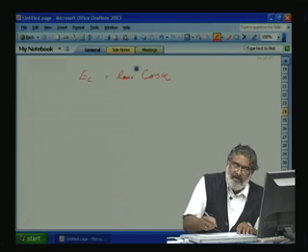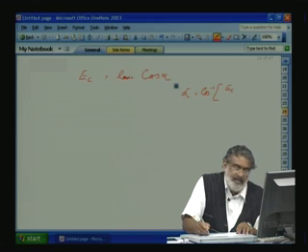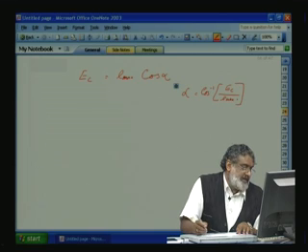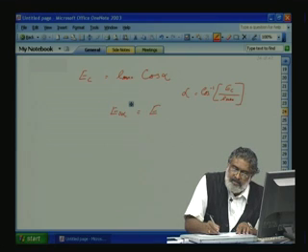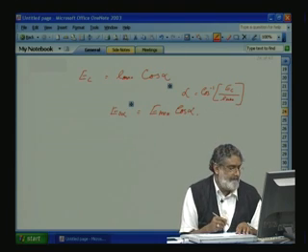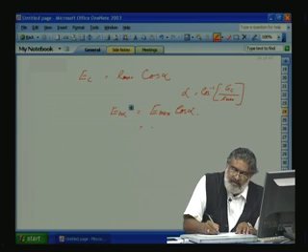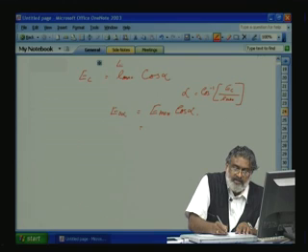Now, what is alpha? From this, alpha is equal to cos inverse of EC by E maximum. Now, our output voltage E0 alpha is equal to E0 max, the maximum for firing angle alpha equal to 0, into cos alpha for a 3-phase fully controlled converter. We substitute this. Our control voltage EC is proportional to cos alpha.